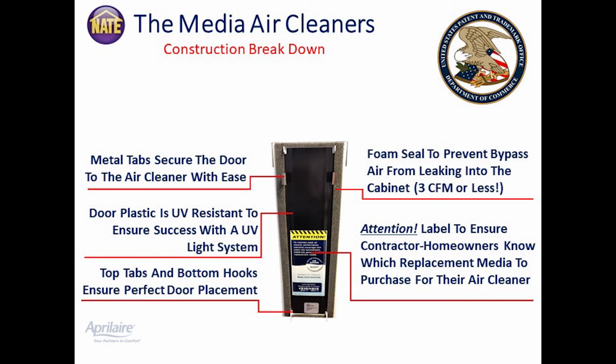These are in unconditioned spaces. You want to make sure that you've got an installation that's not pulling that crawl space or attic air, or suppose even garage air, or in many places, even the basement air is not particularly nice, into that HVAC system. If you are using UV lights, either UVA or UVC, whether germicidal or odor reducing, that plastic has a black material in it that makes it UV resistant.